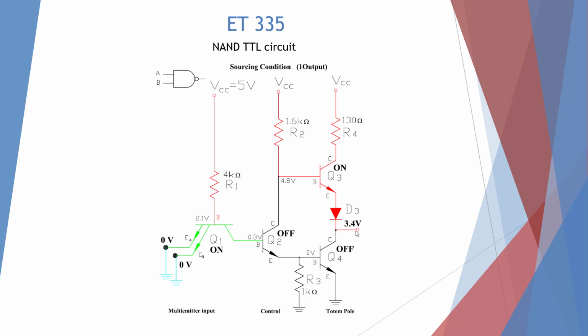And you notice here 3.4 volts is not 5 volts like our TTL. That's because this circuit is taking up a lot of that voltage. So we're not going to get our 5 volt output. We're going to get a nominal 5 volts, which we'll look at the specs later, but it's going to be close to being high, but it will never be 5 volts.